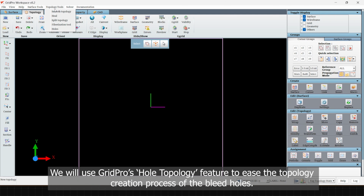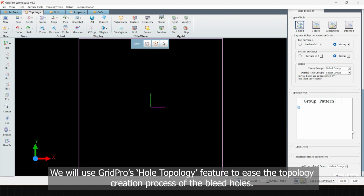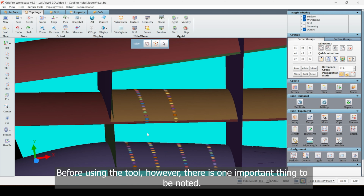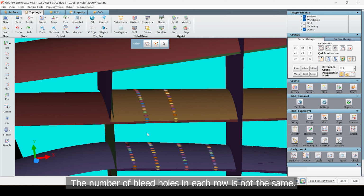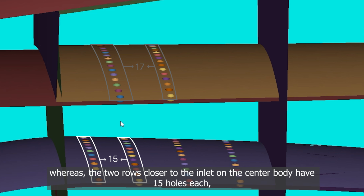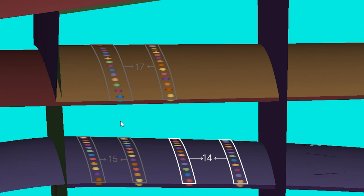We will use GridPro's hole topology feature to ease the topology creation process of the bleed holes. The tool has the ability to automatically create the blocking and the internal surfaces for the specified holes in the geometry. Before using the tool, however, there is one important thing to be noted. The number of bleed holes in each row is not the same. The two rows on the cowl have 17 holes each, whereas the two rows closer to the inlet on the center body have 15 holes each, while the two rows farther away from the inlet have 14 holes each.